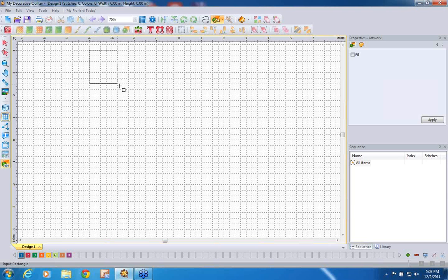So you're going to click and you're going to drag down to the right until you get to -375 on the left, which is right here, and +375 on the top. So that's right there. Again, you don't have to be perfect. Just somewhere in the ballpark will get you there because it's going to snap to those grid lines. So there's our first artwork box.